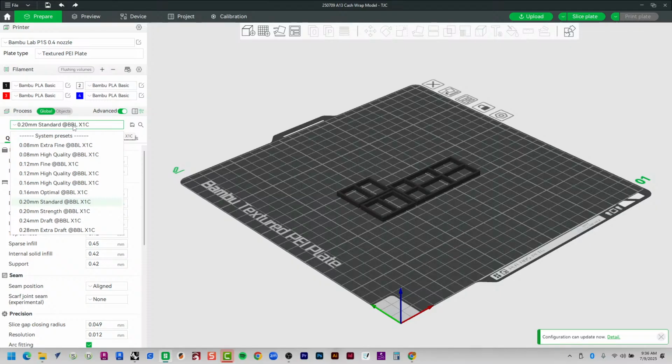So when we 3D print, we're 3D printing one layer on top of another, on top of another, on top of another. The finest layer height that we can have is 0.08. That means every layer is very tiny. Every time it moves up, it only moves up 0.08. Okay? When we do it something that fine, it's going to take longer.